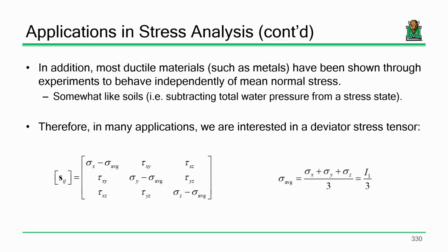There are a number of applications where you've probably already done this in some fashion or another in some of your classes. And I'm sorry that I relate everything to civil engineering because it's what I know. But for you geotechs out there, you've done this before when you calculate effective stresses in soils. When you calculate effective stresses, you subtract out the pore water pressure, because that's that hydrostatic stress. You don't really care about the total stress. You care about the effective stress. So you take out that water pressure, and you probably know what I'm talking about.